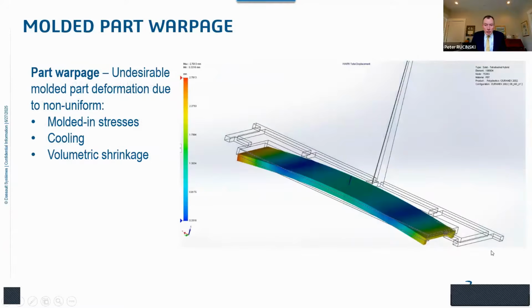And then maybe one of the ultimate defects that occurs in injection molded parts: part warpage. This is when you're just trying to simply mold some kind of a flat part, and when the part comes out of the mold, it's shaped like a potato chip or a tortilla chip or something like that.